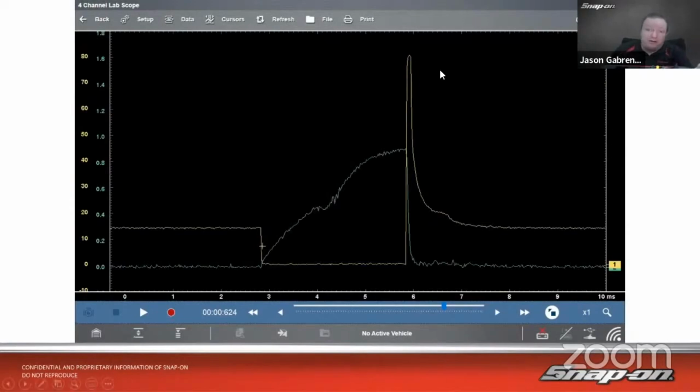If I don't get a peak at all, that indicates it really didn't open because my coil didn't hold that energy. It works on the same principle as an ignition coil. Then it comes down, and then we have this other little pintle bump right here. This is going to be the actual point where the pintle closes, snaps shut, and stops spraying fuel. When it does that, that little mechanical stop jolts a little extra juice back out of the coil, so we get that little thing they also call coil oscillation, and then it flattens out.